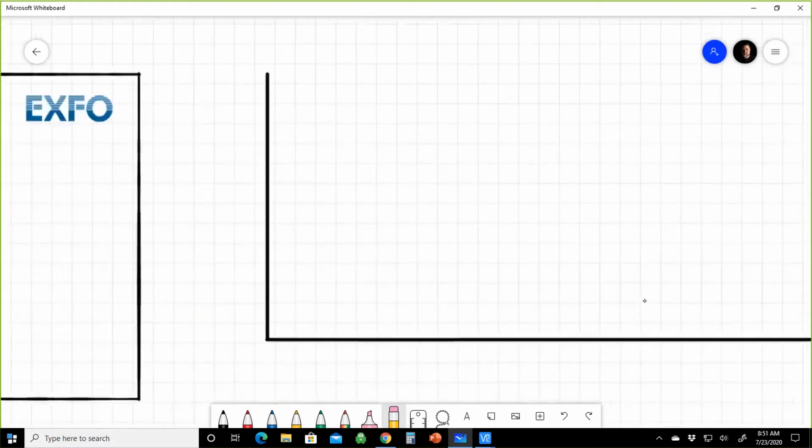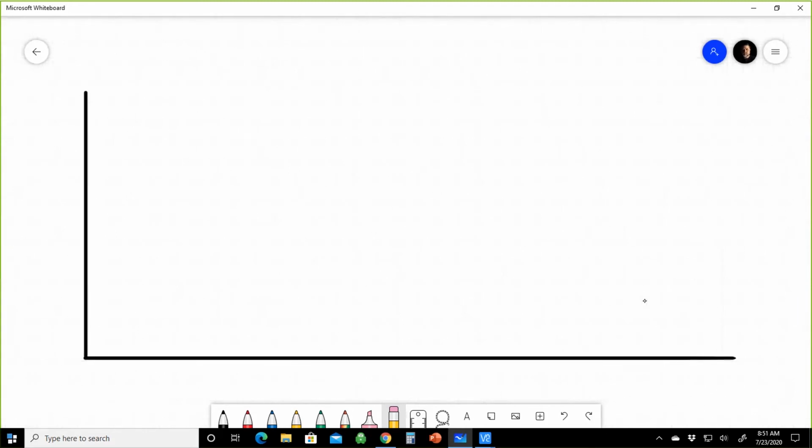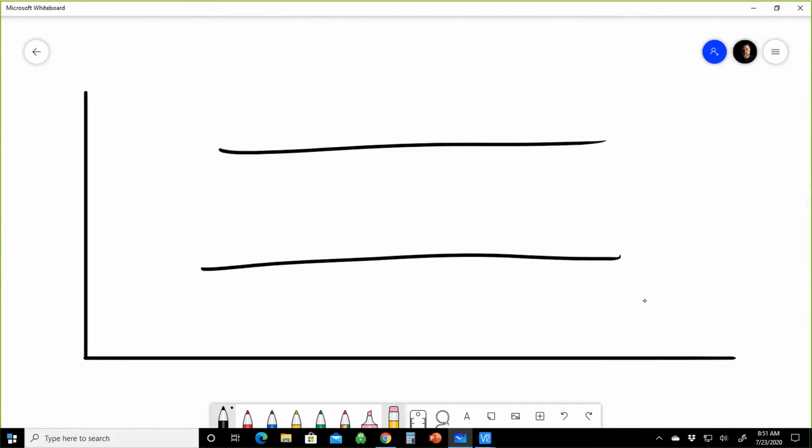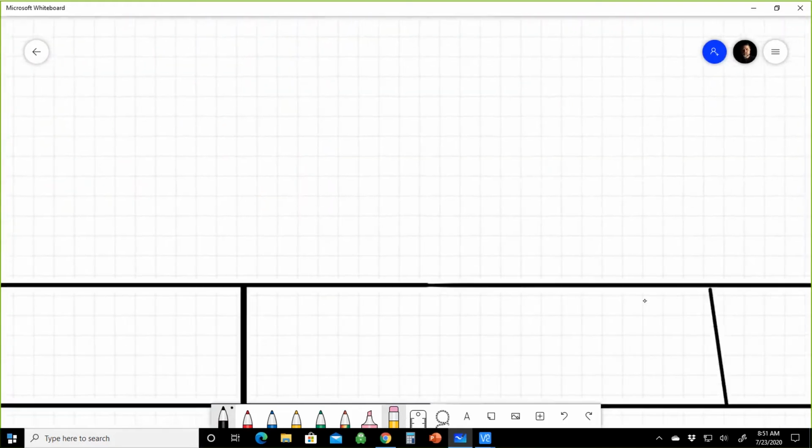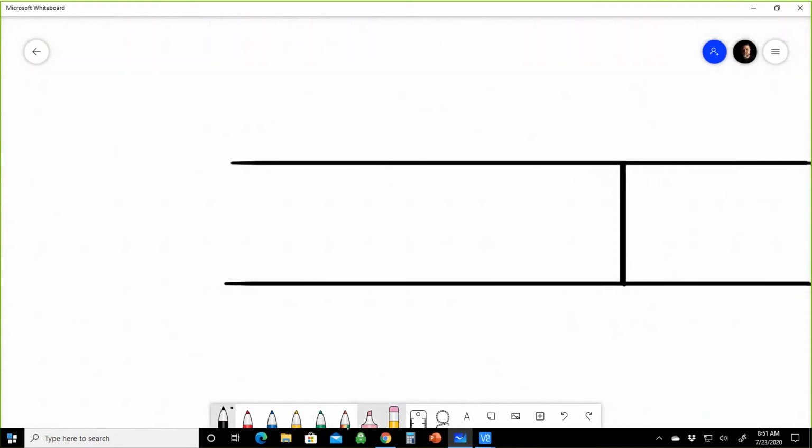So when we're looking at an OTDR, what does an OTDR do? An OTDR sends out a pulse of light. So you basically have a fiber here. In fact, let me go to a different screen so I'm not drawing on this one. Essentially it sends out a pulse of light and interprets the backscatter. And so this pulse of light comes out. Of course it's bouncing and whatnot, but basically it sends out a pulse of light.